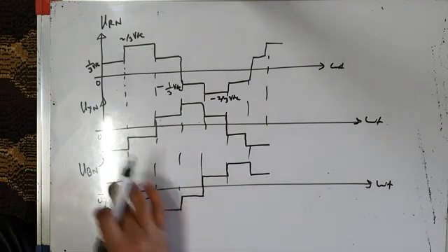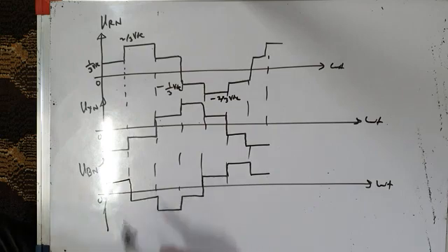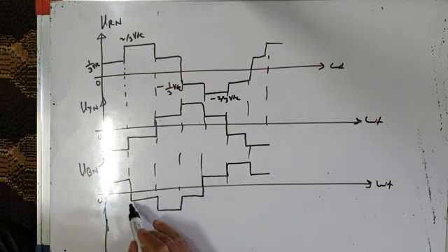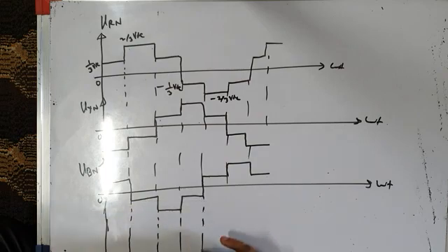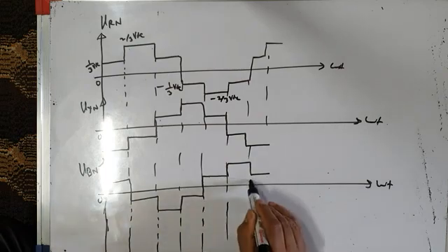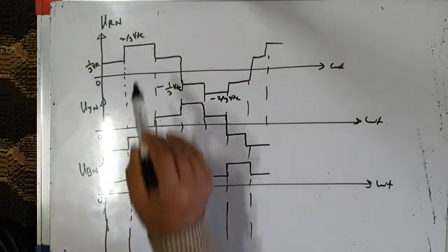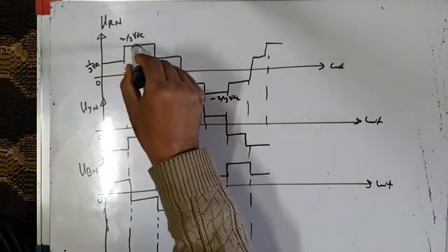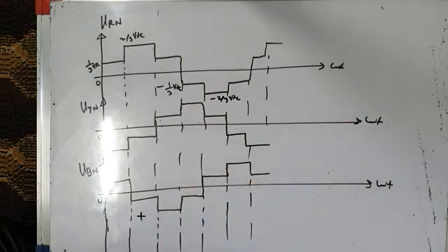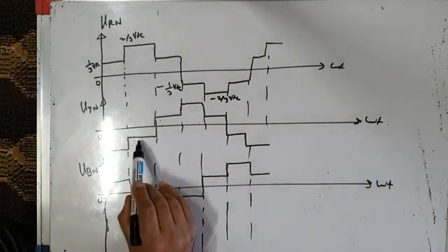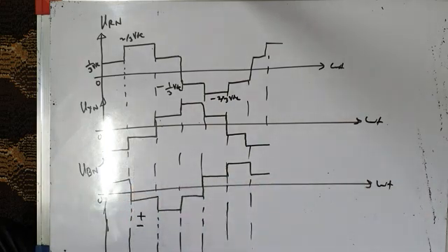This is my phase voltage VBN. So these are my three phase voltages. Now interestingly, if I start from here, let me take these 60 degree intervals each. Here my VRN is positive, so I will write plus, that was phase leg R is on. VYN is negative, minus. VBN is also negative, minus.